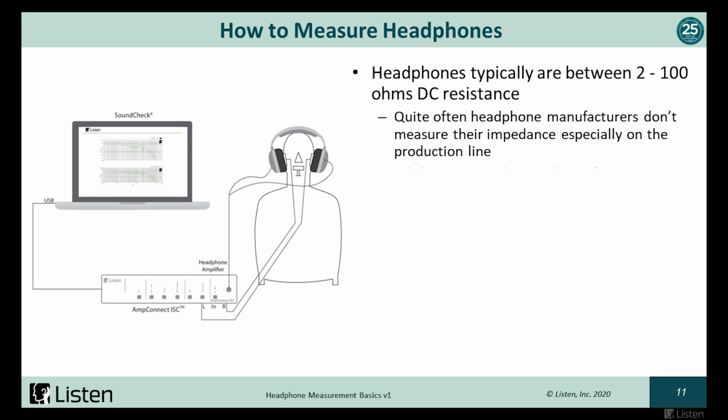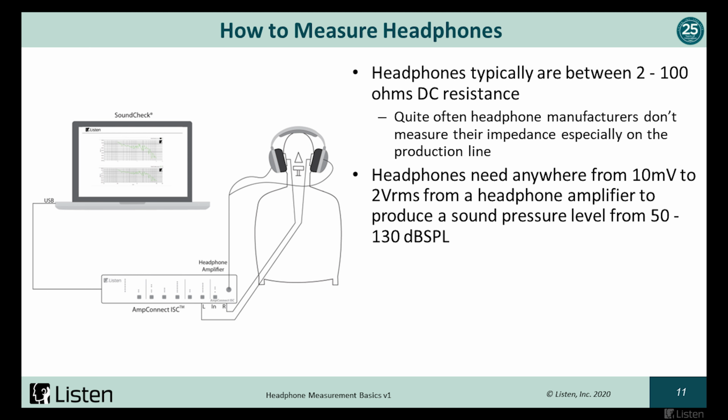And it gets a little tricky, especially if you have a wired cable with a common ground. So generally people don't do this now. Of course, fewer and fewer wired headphones are coming out today, so that's another reason why impedance is not typically measured. But it is really important if you're measuring the raw transducer and you're trying to design the best earphone transducer possible before you add the electronics.